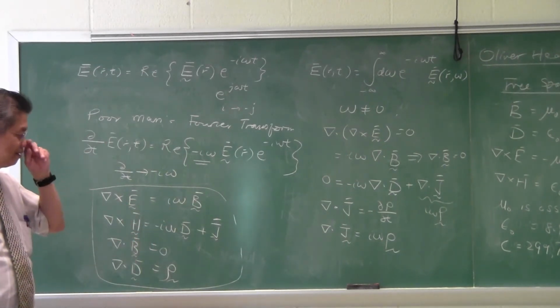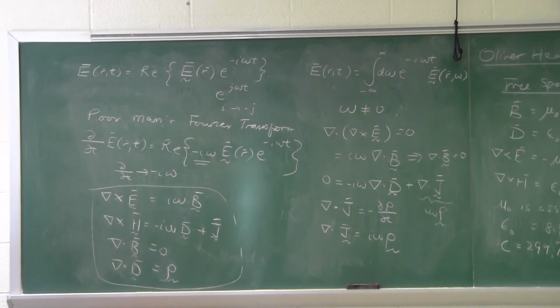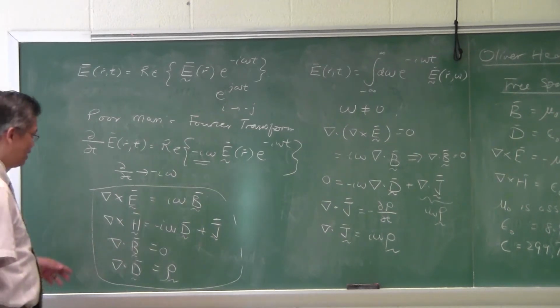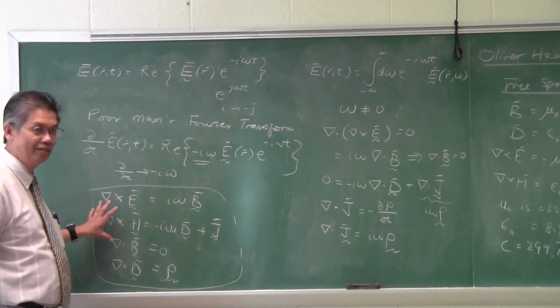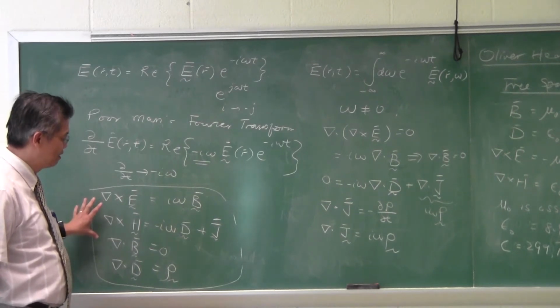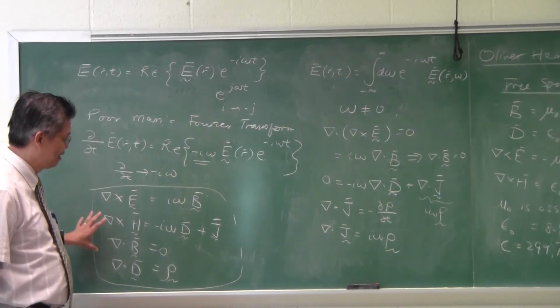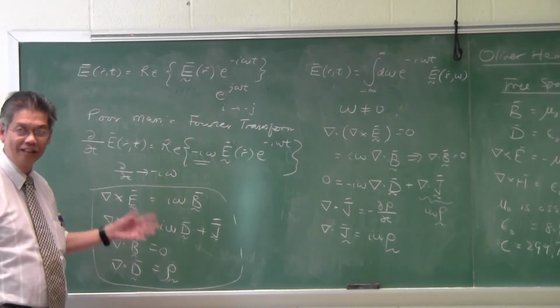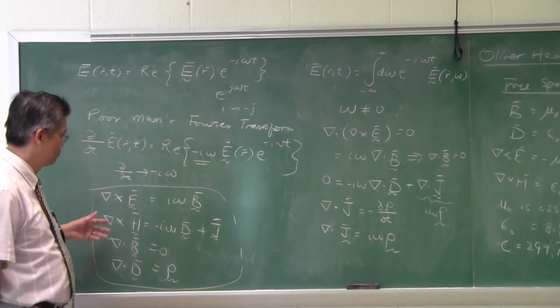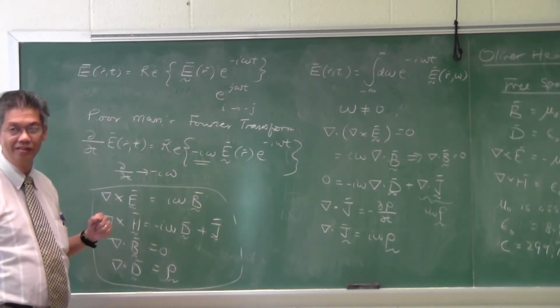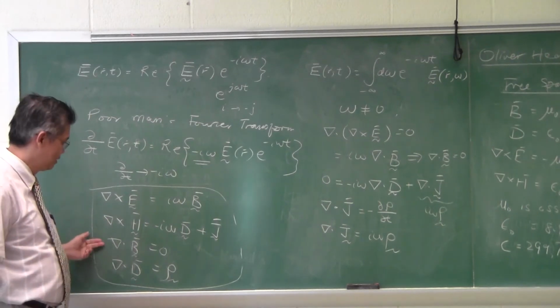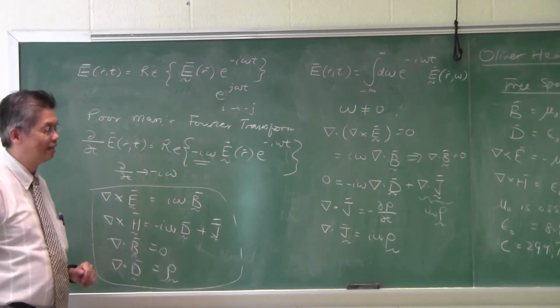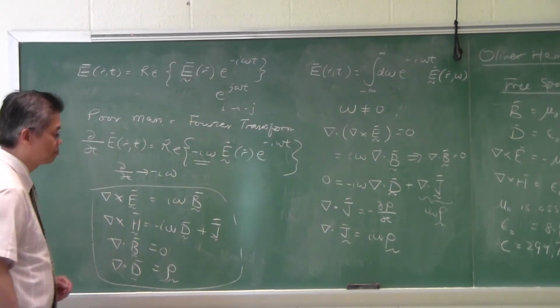So this is a very complicated thing in the field of computational electromagnetics, in the sense that if you arrive at a solution for Maxwell's equations valid for non-zero frequencies, and you let the frequency drop to 0, the solution is not necessarily valid, because it did not take into account the last two equations. Okay?